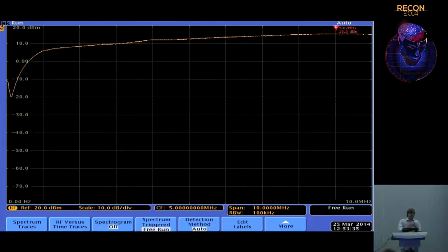So it's using this direct inductive coupling instead of what we think of as traditional radio propagation, and that's why you can't get very much range out of low-frequency RFID systems. Because of that, just plugging in an antenna and expecting it to work with RFID doesn't really work. And I'm just talking about low-frequency and high-frequency RFID, where high frequency is really down around 13 megahertz. There are different types of RFID systems at much higher frequencies that do propagate over greater distances.